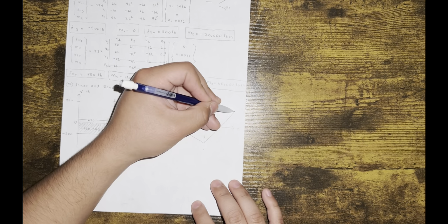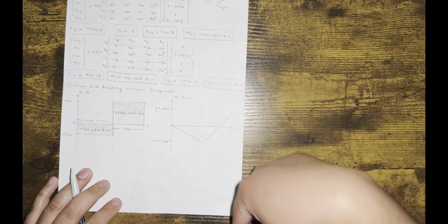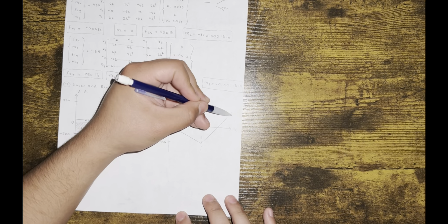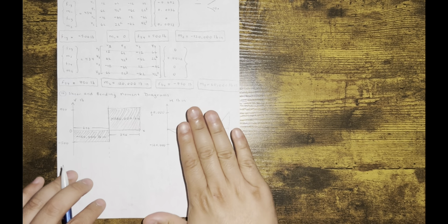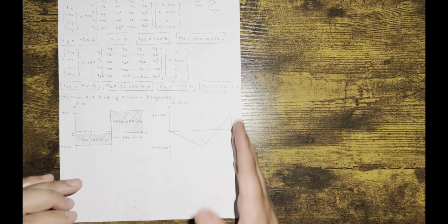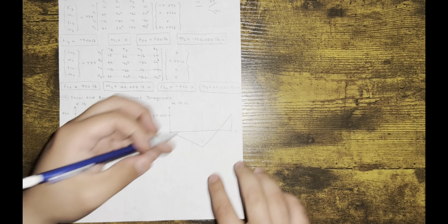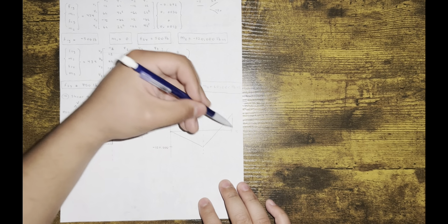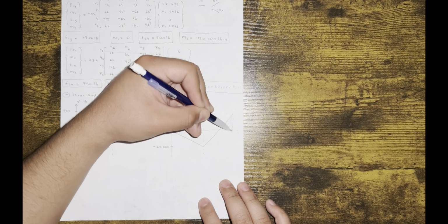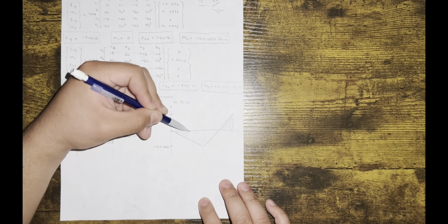The 60,000, when it's positive, when it's counterclockwise, a counterclockwise moment will push you down. That's what I hate about these courses, right? You got to know all this stuff, but when you're drawing the shear, the bending diagram, counterclockwise pushes you down. I mean, this whole time we've been taught that counterclockwise is positive, right? So you might think to push it up even more, but no, that's not the case when you're making the diagram. So in this case, 60,000 pushes us back down to 0, and boom. So there's a positive moment. This is a negative moment.